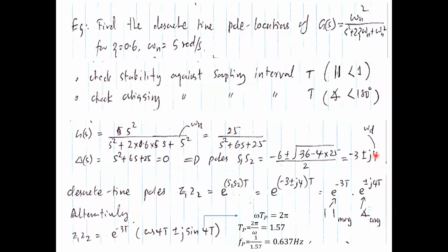You are dealing with a 4 radians per second signal. So you have to sample it at least at 8 radians per second. If you work with radians per second, radian frequency, it's 8 minimum, but preferably maybe more than 30 radians per second. You have to get enough samples, right? Okay, that part is clear.